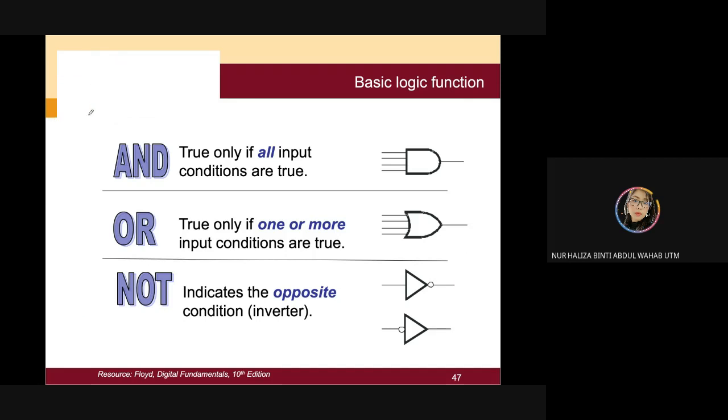But now you apply it to the gates, and normally we will use this kind of symbol, which is the NOT gate. But sometimes when you are going to minimize a combination of circuits, you will have a method to put the bubble version.